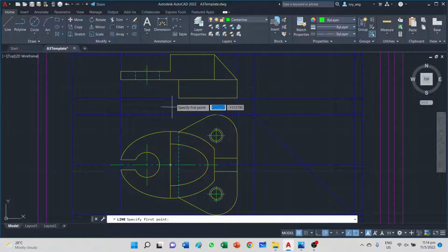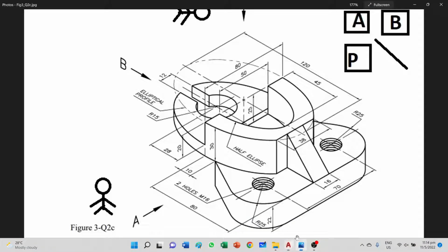And the next thing that we'll look at is this region over here. It steps down and it goes across. How do I know that? Because when you look closely at the drawing, from the top surface of the ellipse all the way down to the base on the inner side is 25 millimeters. So what happens is that it's half the thickness of this protrusion over here.